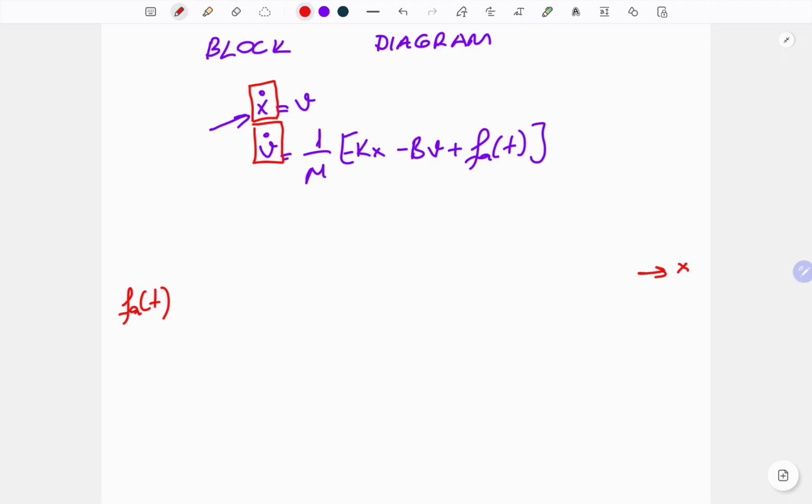To clarify the block diagram drawing, let's start from the final part. x can be obtained from x dot. So if we take an integral of x dot, we can obtain x. So we need an integrator block from x dot to x. And x dot is also equal to v. So that part explains the first equation of the example.